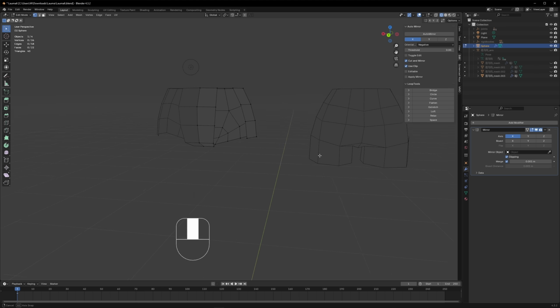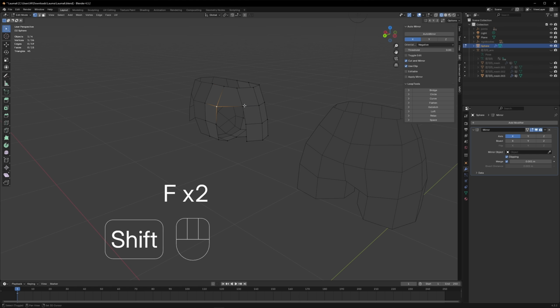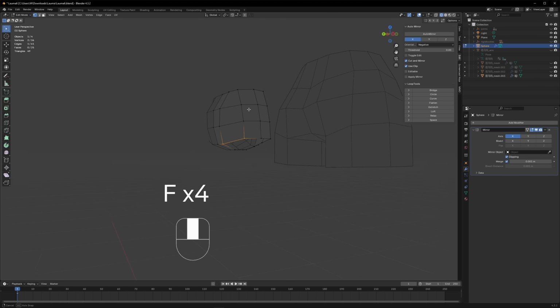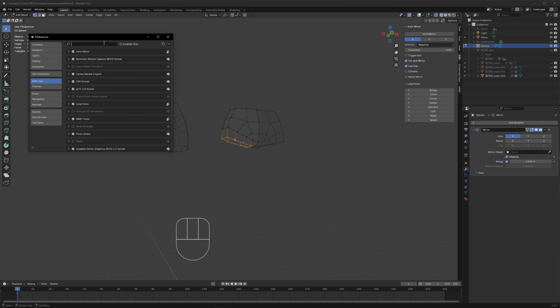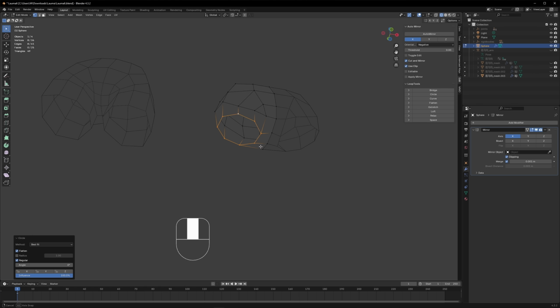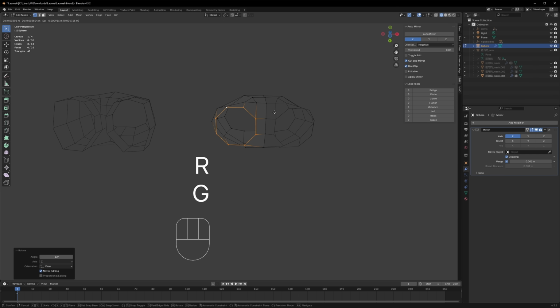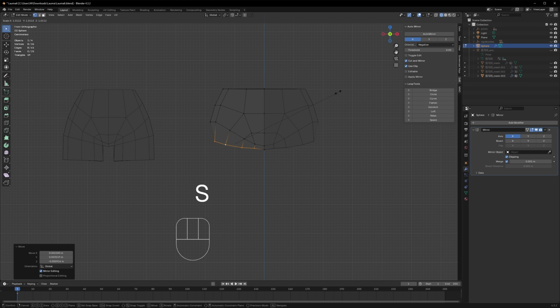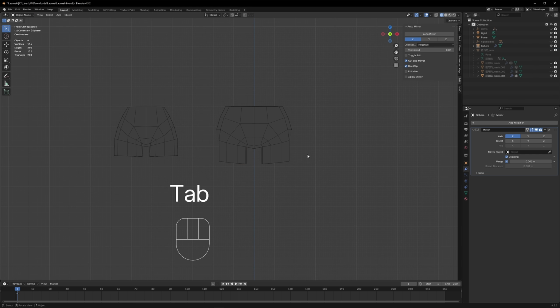Here in the back, we just gotta fill in these faces. And it's just 3 basic faces, nothing fancy. And after doing that, we already have our loop for the legs, we just gotta fix its shape. Make sure the Loop Tools add-on is on in your preferences. Then with that leg opening loop selected, go to the Edit tab on your right hand side, and under Loop Tools, press circle and rotate it into place. Now extrude that down once and scale it down on the Z axis so that it becomes flat. So now what we have is a recreation of the mesh face for face.